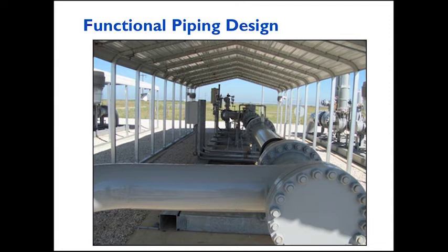And then out the backside, we come off that. We have a 90-degree turn down. And then at the bottom, underground, there's another turn. So if you look at all the turns we're making coming into the entry to that ultrasonic meter tube, we probably have 360 degrees worth of rotation.